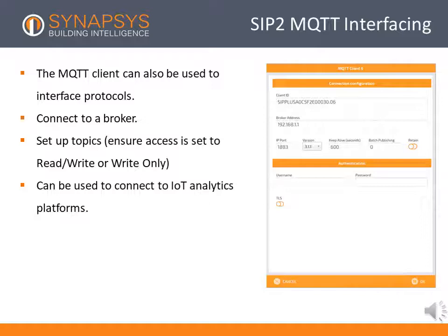To interface over IoT, there are 2 options, MQTT or REST. When using MQTT, configure the driver as described previously in the module. Ensure when points are created, they are set to either write-only or read-write to send data to the MQTT broker.